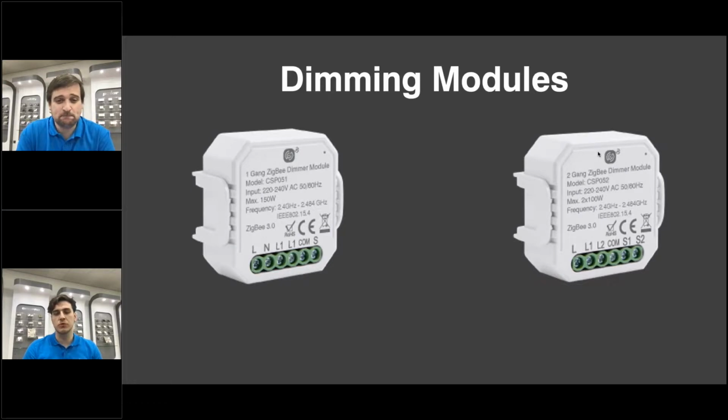With these dimming modules, it's probably important to mention that you do need to use retractive switches. You can do it without them and use the app. However, it does cause a bit of confusion when they're starting to switch and dim. So we do say that you need retractive switches. Again, it doesn't matter what the retractive switch is, as long as they're wired in the way that the instructions say. So these are wired devices.